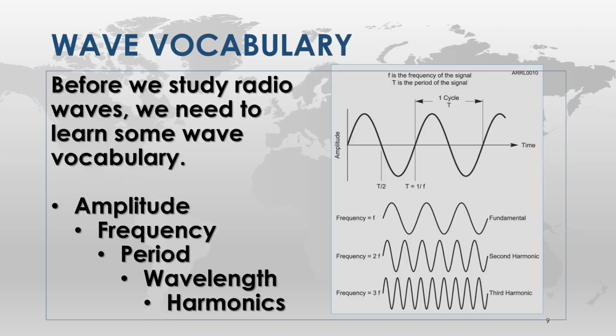And harmonics, okay. The third harmonic, your antenna is resonant at a set frequency. At the third harmonic, a multiple, it will also be resonant. So a 7 megahertz antenna, which is 40 meters, would be resonant at the third harmonic, 3 times, at 21. I'm also going to be able to use that antenna at 21 megahertz, the third harmonic.